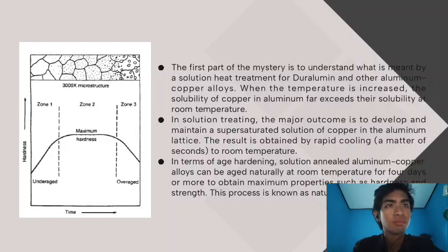Detection requires the submicron resolution of the transmission electron microscope. The first experimental discovery of coherent precipitates occurred independently from X-ray diffraction studies by Andre Guinier and G. Preston in 1938. The zones of coherent precipitation are now referred to as Guinier-Preston or GP zones. The increase in hardness with time is known as precipitation hardening or age hardening.